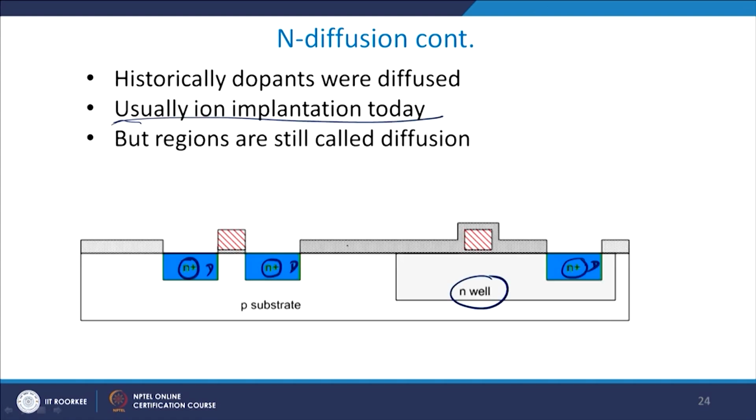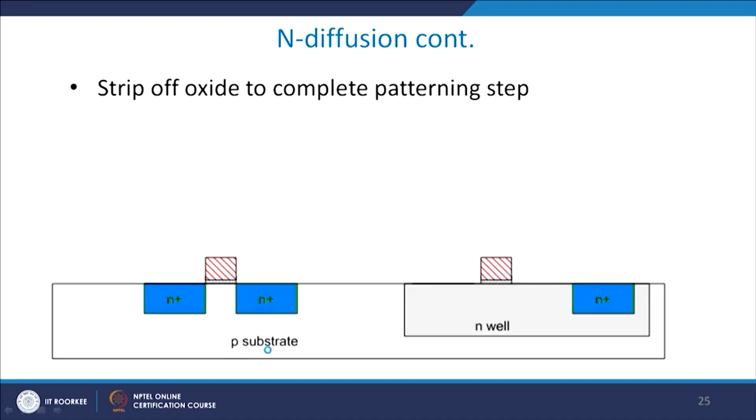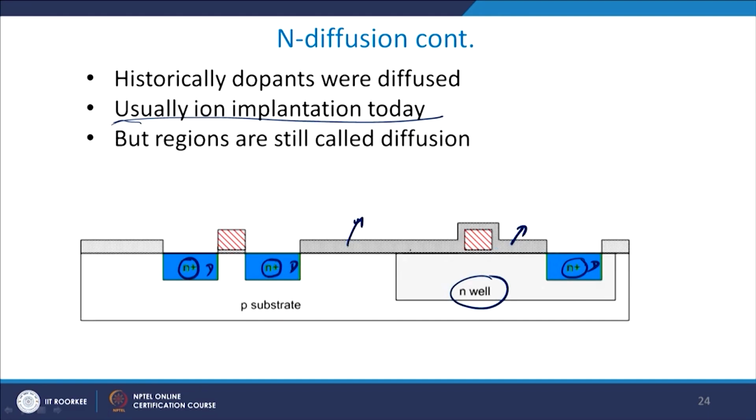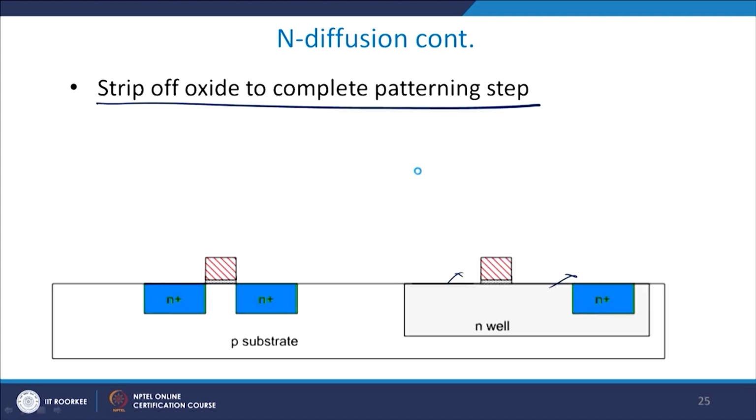Now what you can do is strip off this layer of polysilicon, right. In the next slide you see I have removed this polysilicon. You remove the oxide layer, and all the oxide layer here has been removed. If you go back to your previous slide, this was the oxide layer which was there. By doing HF etching or using some other technique, I can remove this oxide layer directly and I get almost devoid of any oxide layer in this case, right.